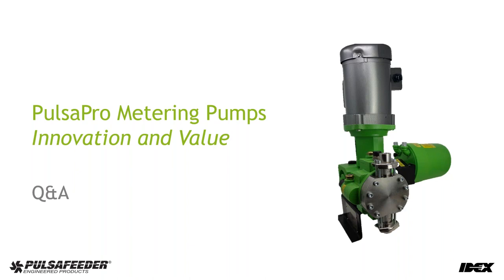So worth mentioning, Jeff, that in the event of a system issue and you're troubleshooting, trying to find out where the problem might be, having that insight into the hydraulic bypass condition of the valve or of the pump can be very useful in trying to figure out where that problem is. Right. So you can identify, number one, if it's your pump or your system. If you're bypassing, then your pump is either not set correctly, you've had a system change, or there's some type of blockage downstream.